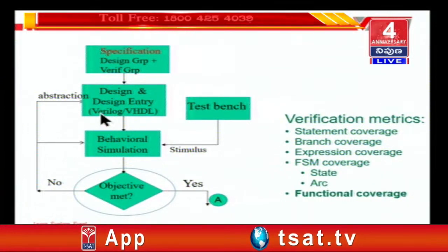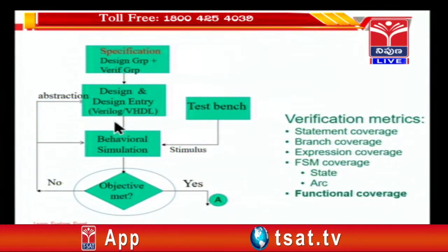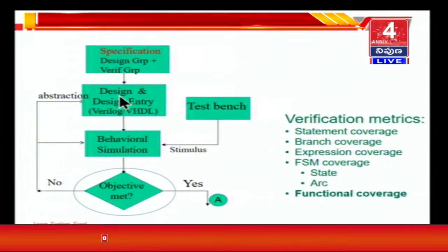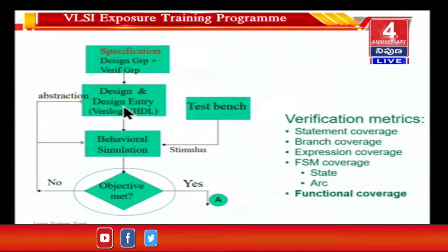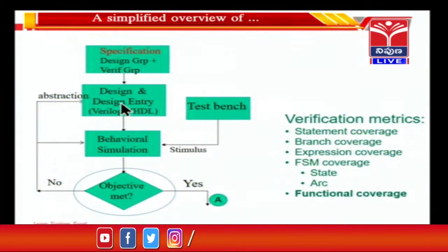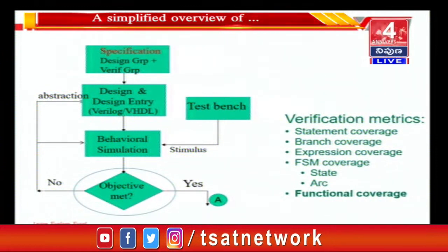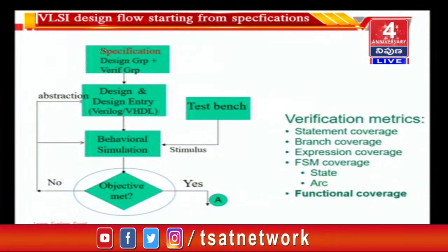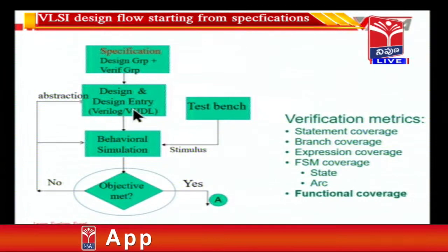You can write Verilog code at the gate level to describe an AND gate. You can write it at the data flow level to describe an AND gate, and you can write it at the behavioral level also. Sometimes for very simple things, behavioral level and data flow level may be one and the same. Okay, this is what it is.